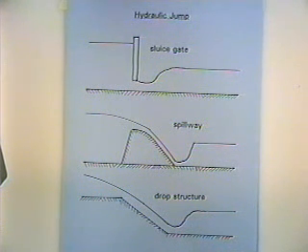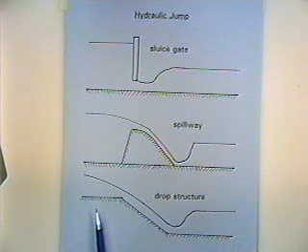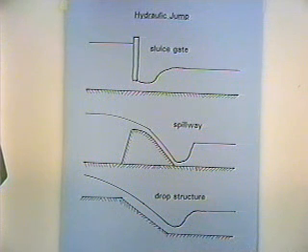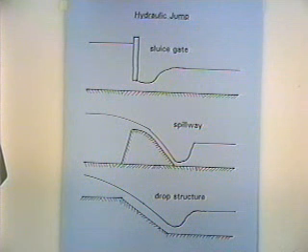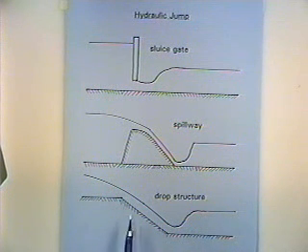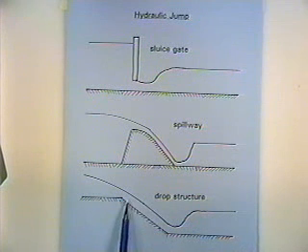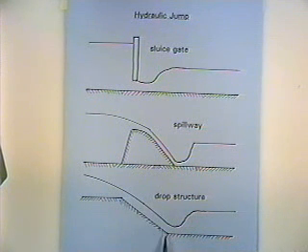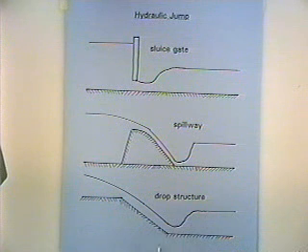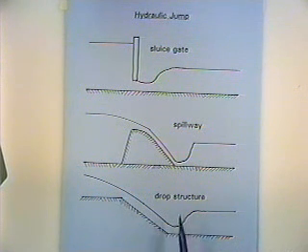A drop structure, in drainage and flood control channels where the topography is such that if you just put the channel on grade of the topography, the velocities would be such that there would be tremendous erosion, and so you can have a drop structure where you drop a lot of the elevation difference in a concrete structure, and again let the energy dissipate here. And so again, just examples of hydraulic jumps, and the critical flow concept is very pertinent in analyzing those types of situations. We'll come back to that and look at it some more as we go, but just do